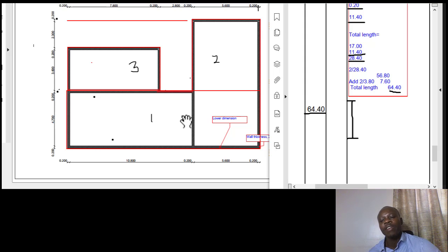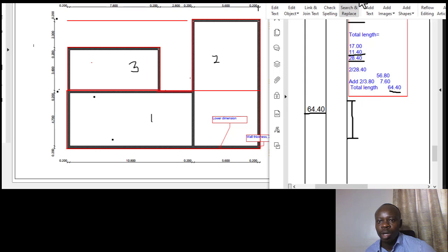So you add 75 to that particular girth moving forward. But for now, for what you have, the 150 millimeters thick, it's falling in a stage of exceeding 75 millimeters but not exceeding 150 millimeters. Okay, perfect. So once that is discussed properly, we'll move ahead and make our description for that particular formwork. Okay, so we'll go ahead and make our description, and then we see what follows.